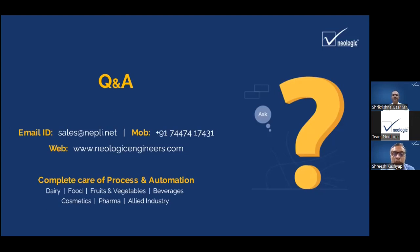Yeah, good. There was one question from KN Singh. He's asking, is there any alternative to hydrogen peroxide for sterilization of laminates? But I think, of course, as we said, in our case it is actually sterilized using gamma rays, and the laminate sterilization happens in the form-fill-seal kind of fillers, that is, the aseptic carton fillers. Those are different kinds of fillers, carton fillers. We are talking about bulk aseptic filling out here. But maybe you would like to take this up also, Sri?